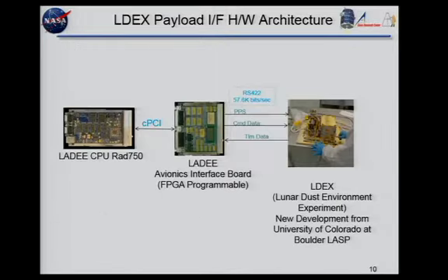Okay. And then next, the ALDEX, the ion detector, was pretty simple, RS-422. The only thing that they had that was different was a pulse per second, and they were using the pulse per second to match up to a time tag that we sent them so that they would know the exact time, for synchronicity. So when they got the time tag, it was a little bit after they had gotten the pulse.